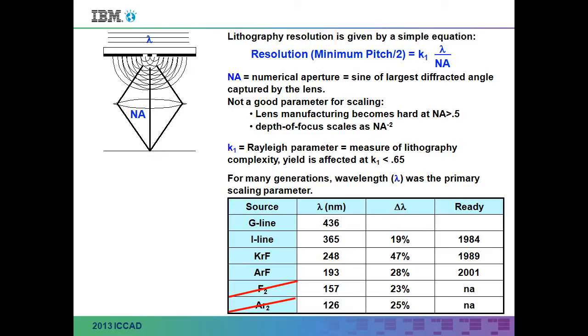So starting in the domain where lithography was, quote unquote, easy, the basic resolution. As I already mentioned, lithographers measure resolution, for reasons I still can't quite understand, in half pitch, right? So the center to center spacing of a feature divided by 2 is the critical dimension that we quote resolution in, and that's given by this Rayleigh constant times the wavelength of your illuminator over the numerical aperture of your projection lens. And I drew a nice little cartoon here, right?